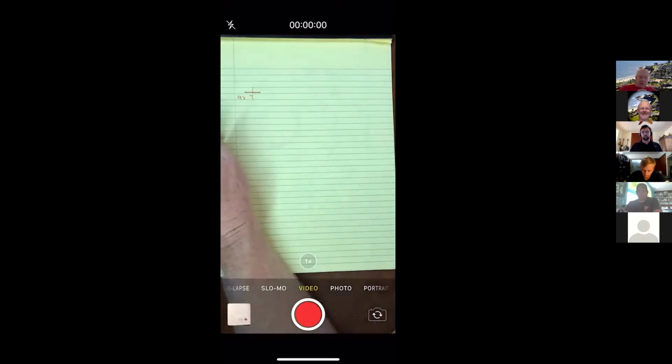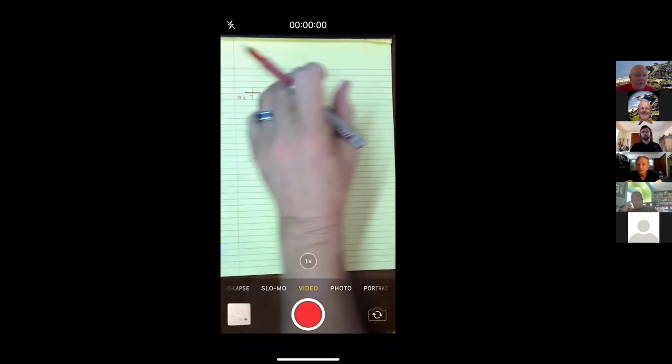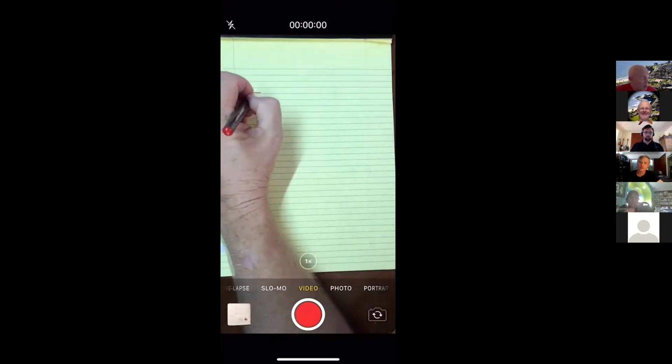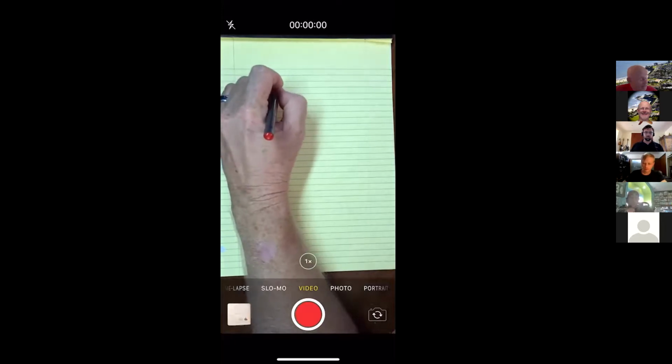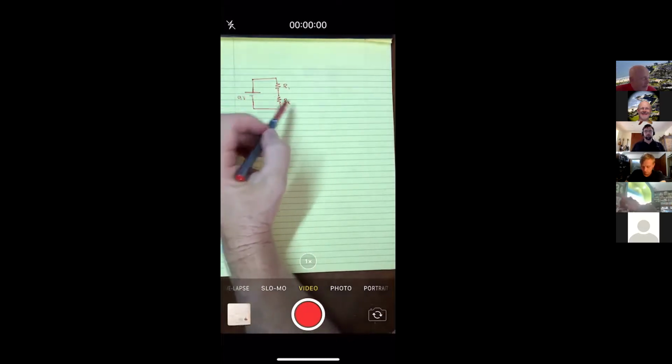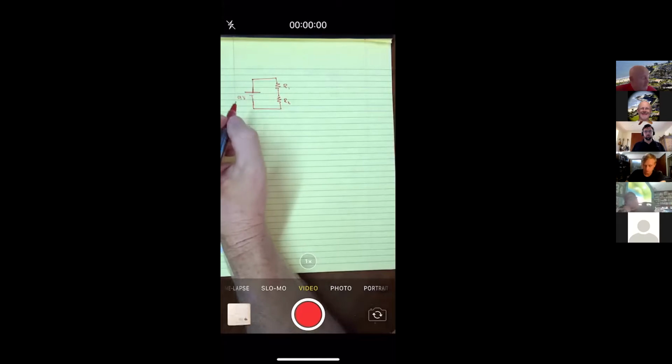I'll tie this in with your circuits class, because this is how the circuits class is running right now. As you know, we're all quarantined at home, so we don't infect each other and have a high death rate, right? And Dr. Nick, who does the circuits class, is going to require you to buy a breadboard and a bunch of resistors and capacitors. You might already have them, and a 9-volt battery. He runs all the labs off 9 volts. So maybe the first lab, you put resistor 1 and resistor 2, calculate what the current is going to be, and then you actually build it.